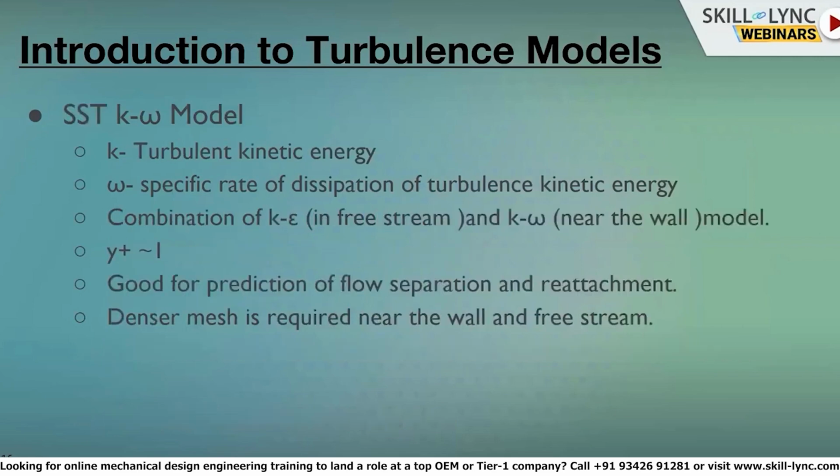And this is another famous model, the SST K omega model, shear stress transport K omega model. This is actually a combination of the first two models we have seen, that is K-Epsilon and K omega. Here also we require y plus close to 1. But one advantage with this model is that it automatically switches between K omega and K epsilon.